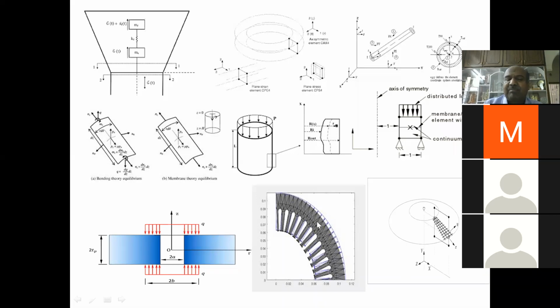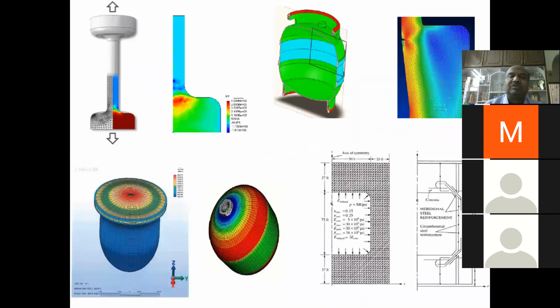This is the electrical member where all the thermal aspects come in, and when voltage is increased, there is a change in current. By that, the temperature change will be there. So quarter symmetry of the model is shown here. Here also, the axisymmetric small section is shown. When you revolve it, it is going to be a 3D solid. So rather than 3D, we do 2D analysis.